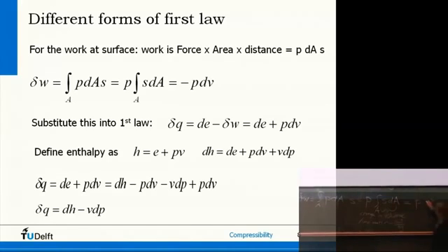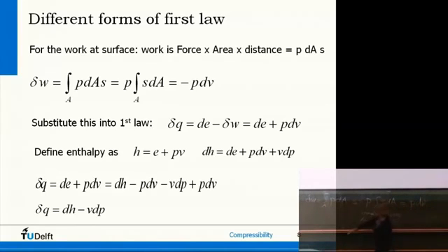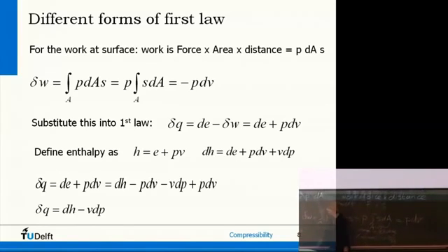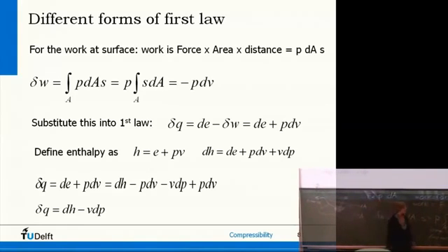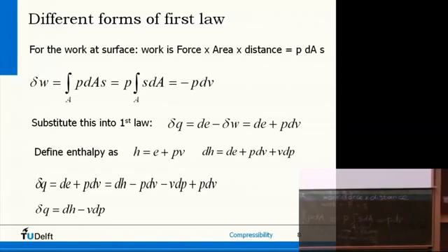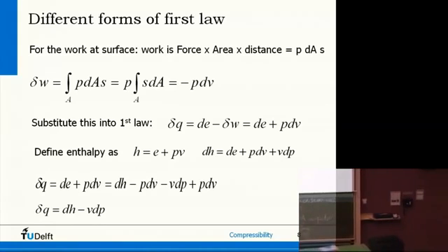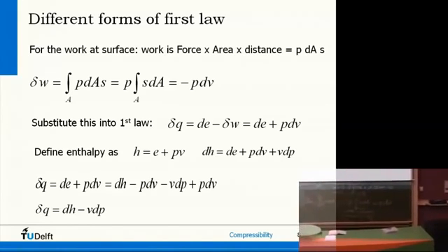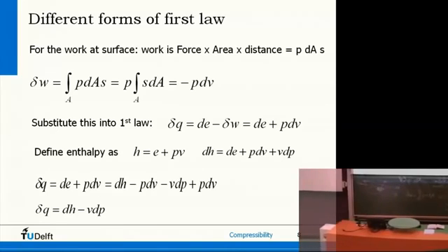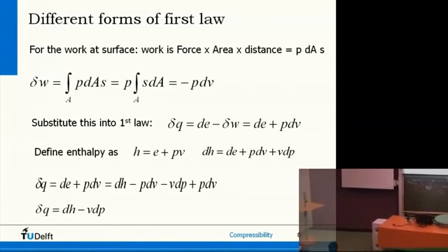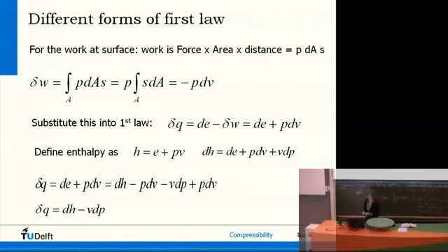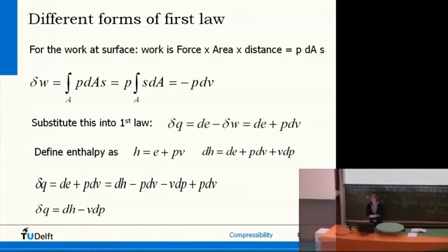And what sign should it have? Is the volume increasing or decreasing due to the higher pressure up here? It's decreasing, so it is a negative sign. So it's minus PdV. So the work done on the entire system per unit mass, you can rewrite to be minus PdV, and this is the curly V, the specific volume. Now we had the first law of thermodynamics stating that dE is dQ plus dW. We can rewrite that as dQ.